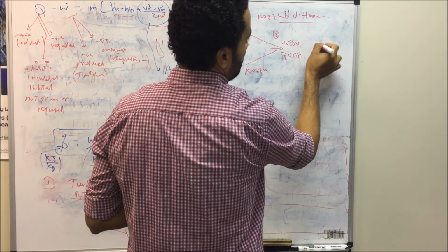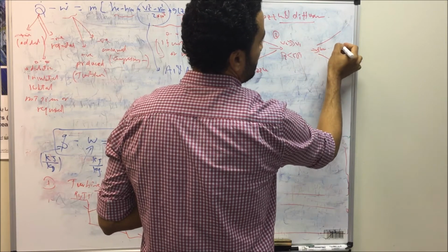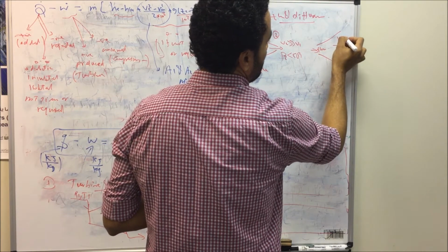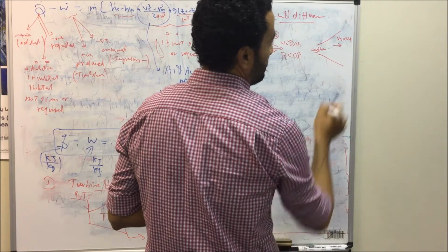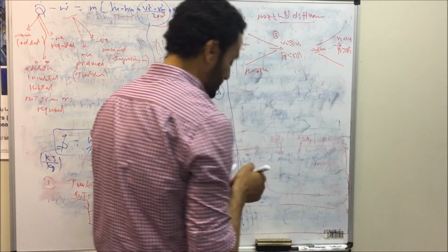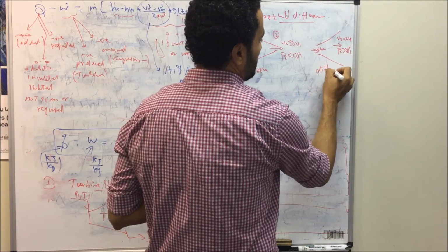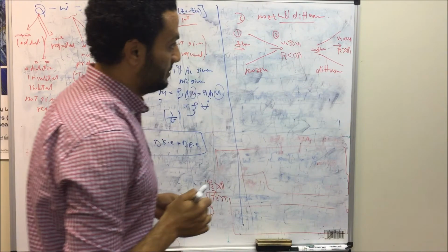When we have a diffuser, the case is reversed. The flow is coming, but the area is increasing in the flow direction, so the velocity V2 is much less than V1, but the pressure builds up through the system, so pressure P2 is much greater than P1, and in this case the system is called a diffuser.